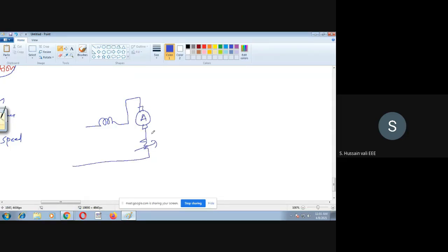So you connect here. So you vary the rheostat position. Then obviously IA will change, EB will change, and the flux production also changes. You see here, in case of the DC series motor, if I vary the armature resistance here, not only the armature current but also the field current changes. It means EB decreases, phi also decreases. That's what I'm saying. There is an arrangement by changing these values. We will understand that. So this is in case of the series motor.